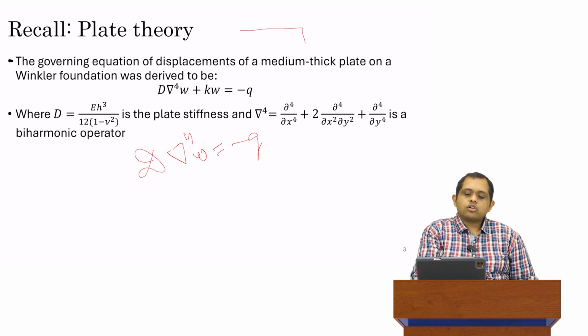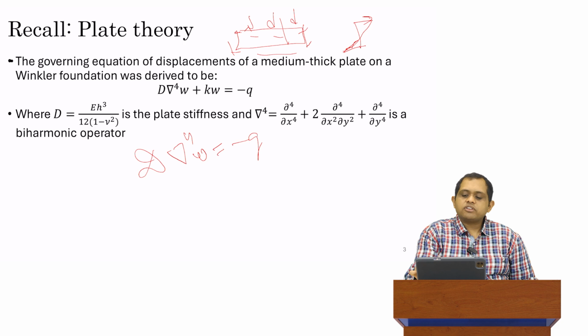So, if this is a cross section of the plate which undergoes pure bending and loading is only allowed in the transverse direction, then the two additional assumptions we make: firstly, all our shear is going to be in the form of bending. If I have a cross section and I draw the stress along this cross section, I'm going to have some stress along this longitudinal direction, but it is not along the vertical or the transverse direction. So we do not admit shear strains. That's one assumption. And the second assumption is that we have a particular plane which is called a neutral plane. At the neutral plane, the stresses are always assumed to be zero.